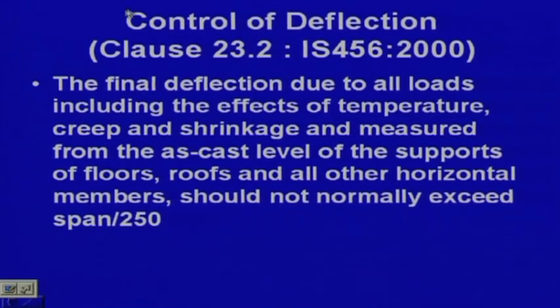One more part is very important, because this is the one that will give you serviceability. I have already told you that whatever I have talked about so far is the limit state of collapse. We are talking about flexure here, for beams as well as for slabs, but there is one more part, that is the serviceability limit state, so that the users will not feel any discomfort.